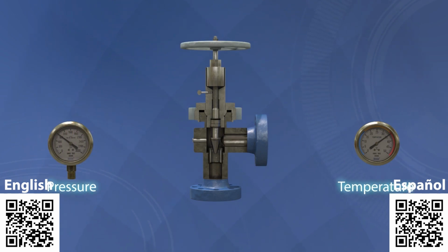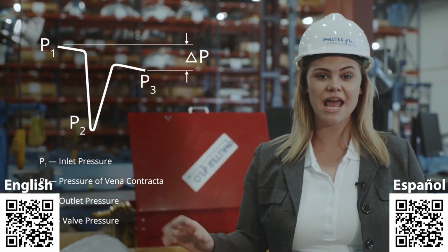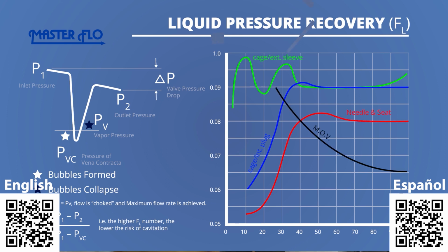If the pressure in the choke falls below the vapor pressure of the liquid, cavitation may occur. When this happens, the pressure is greatly reduced in the valve. The susceptibility to cavitation is governed by the valve FL number, which determines how low the pressure can get inside the valve. In extreme cases, freezing of gas may occur in a choke valve due to hydrate formation. As you can see, the cage with the external sleeve design provides a higher FL over a wider range of valve openings. The higher FL number means a lower chance of cavitation and consequently the risk of damage.